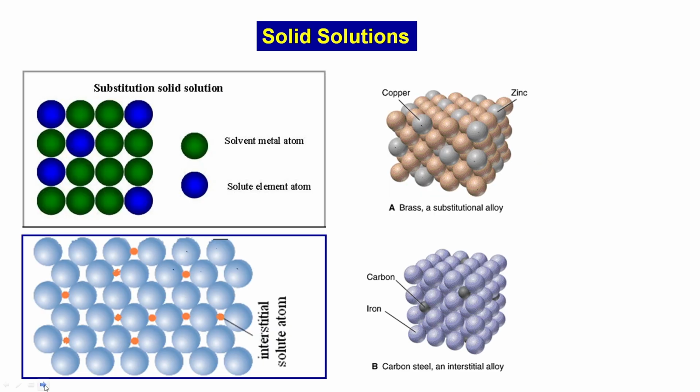And we talked about it. This is a very important concept because solid solutions are widely used in the actual material in alloys. And you can have two types of solid solution. One is substitutional solution, other is interstitial solution. In substitutional solid solutions, you are replacing the solvent atom by solute, and as you know, the sizes of the atoms will be similar. Difference may be maximum 15%. There are defined rules under which the solid solutions can form.